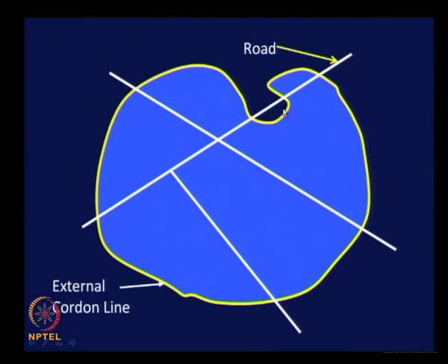Even though to satisfy the condition of matching your boundary with the existing study boundaries may warrant this kind of configuration, still you can modify in such cases to avoid crossing of radiating roads at several points, right. You can just connect your boundary line here so that the crossing point is only one. Such minor modifications can always be done to suit our convenience, right.